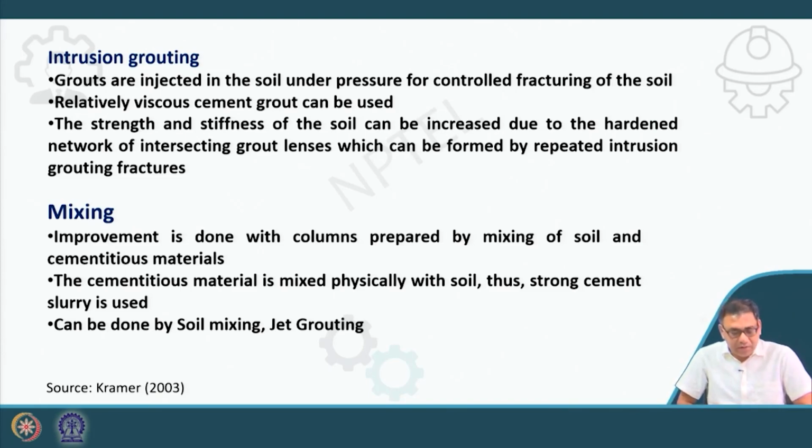Next one is the intrusion grouting. Here grout is injected into the soil under pressure for controlled fracturing in the soil. So that means the grout is injected into the soil under pressure to do a controlled fracturing in the soil. A relatively viscous cement grout can be used.